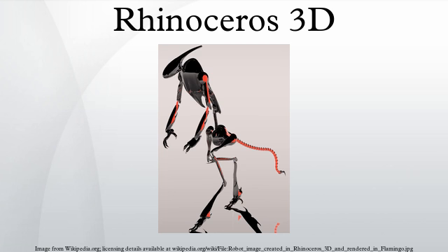Rhinoceros is also compatible with a number of graphic design-based programs. Among them is Adobe Illustrator. This method is best when working with a vector-based file. Start by saving the file and when prompted save as Adobe Illustrator. From there you are able to control the vectors created in Rhinoceros and can be further enhanced in Adobe Illustrator.